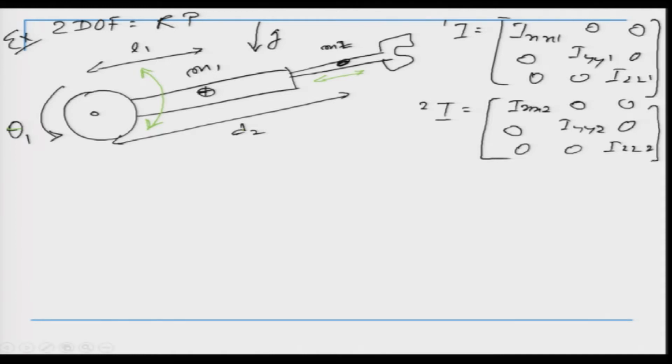Now, note that the robot is going to rotate about the z axis. Okay. So, the z axis is pointing out of the board, or of this sheet of paper. So, when the rotation takes place, it takes place about this axis. So, essentially it is going to be this term which is going to come into effect, the Izz about the z axis always.